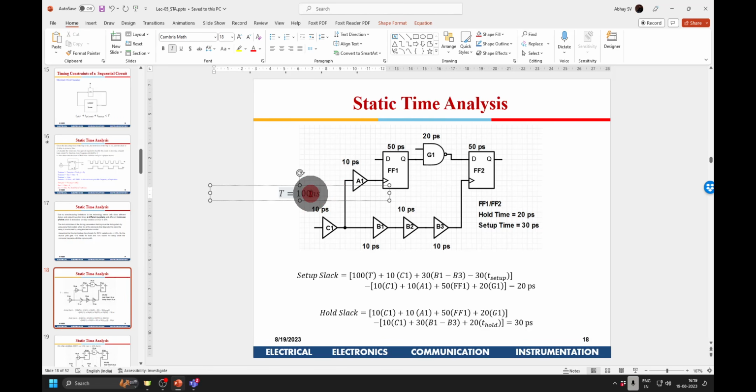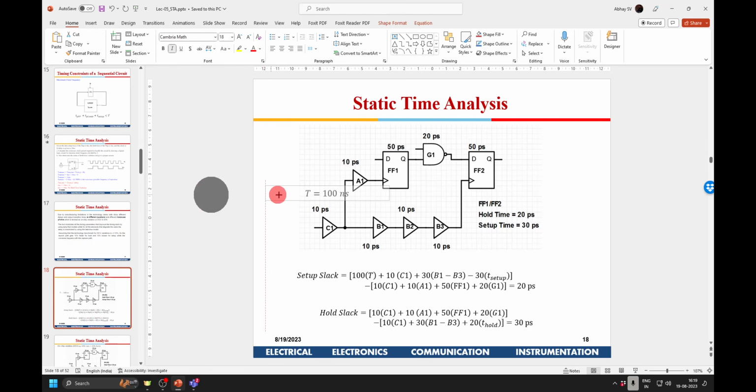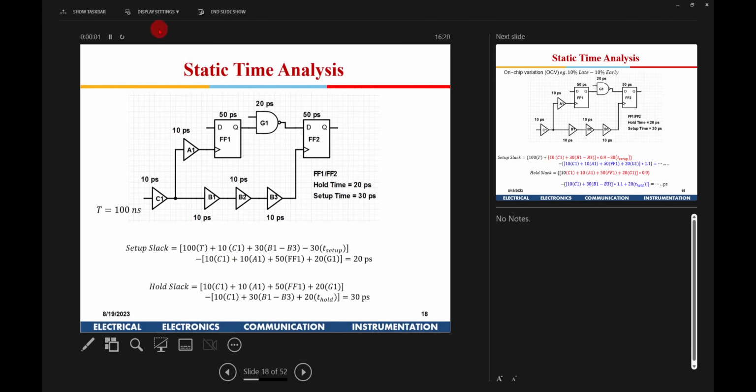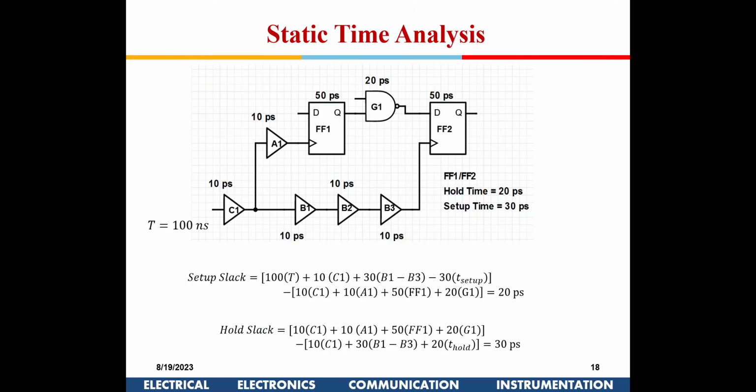For STA analysis, especially for the setup slack analysis, the time period needs to be specified. Without that, you can't calculate the slack. You might be able to compute the total setup requirement of the system, but you cannot compute slack unless the time period is specified. Now the time period is specified.